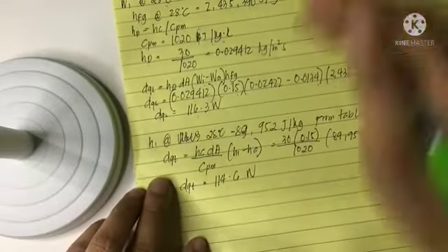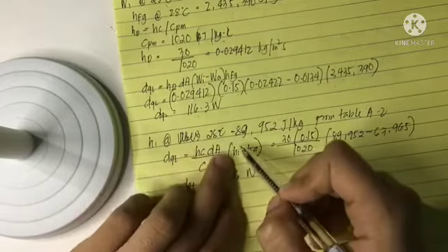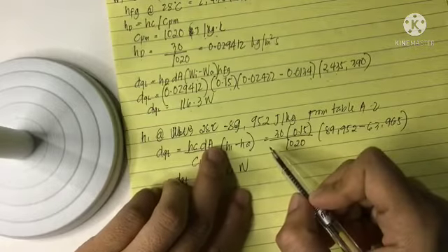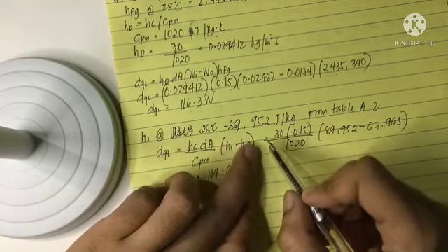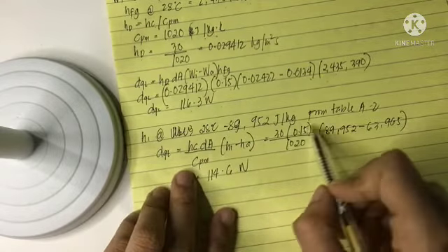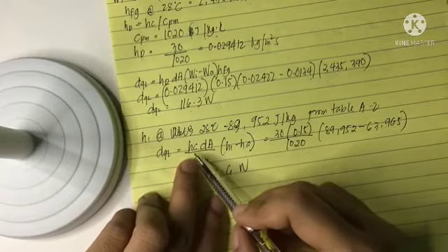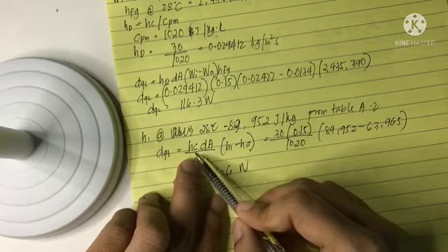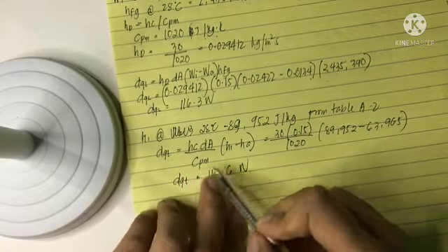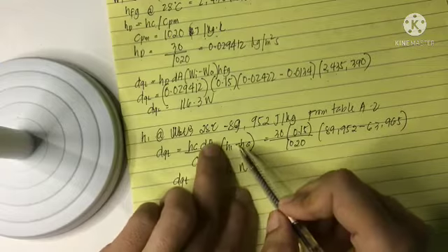So, next, solving for our H1, our enthalpy at 28 degrees Celsius. We have here 89,952 joule per kilogram, from table A2. So, solving for our total heat, we have your convection coefficient times your area divided by your specific heat of moist air times your enthalpy of your air minus your enthalpy at the wetted surface at 28 degrees Celsius.